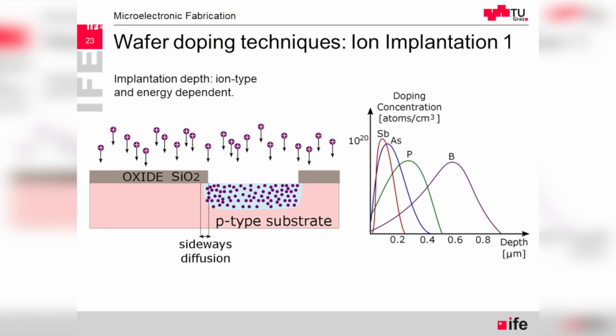The second doping technique is the so-called ion implantation. We could probably spend, again, 20 minutes discussing how the machine is constructed for that. We have to have the generator of the ions, the accelerator, also a selector, so that we only end up with the ions of the type that we want, of specific energy that is intended in the system. So we have this generator of ions that hits the surface of the wafer.